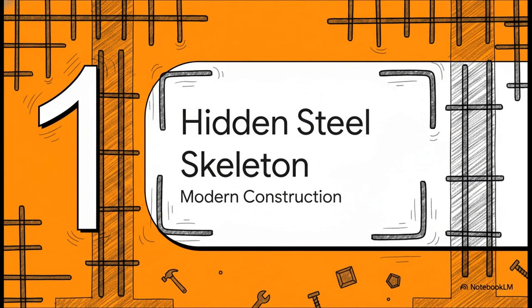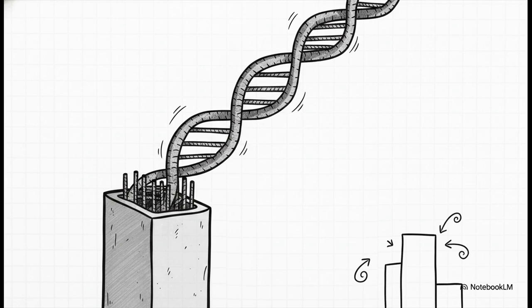Part 1. The hidden steel skeleton, the literal foundation of modern construction. Now, we all know concrete is fantastic. It's incredibly strong under compression, but it's also super brittle under tension. So think of steel reinforcement as a hidden skeleton, providing the ductility and tensile strength needed to hold that brittle concrete body together under immense stress. If the steel is the skeleton, then the bar bending schedule is the exact DNA code that tells that skeleton how to form, where to bend, and how to connect.